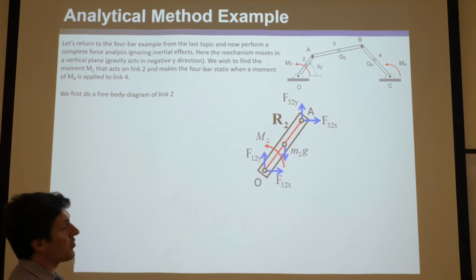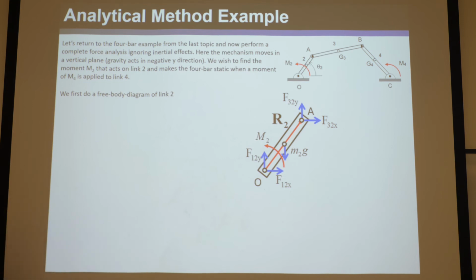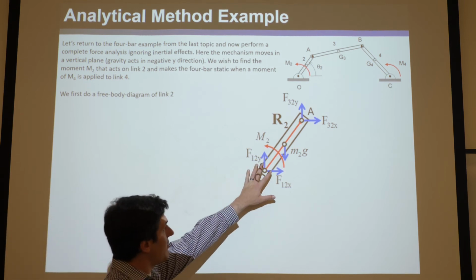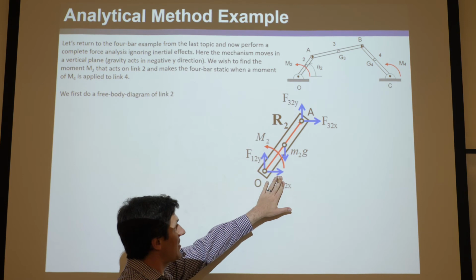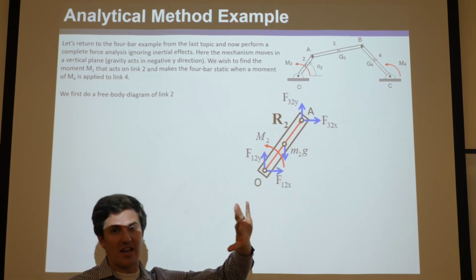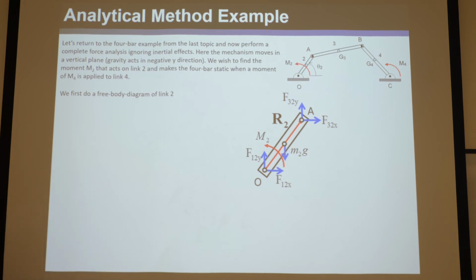Well, no, it's a pin joint, and by the way, you also assume they're smooth unless you're told there's friction in there, so there is no moment that can be imparted on that, just forces, and there could be a force in any direction, but we're going to break it into components. We're going to draw them always positive, and if we stick to that convention and it actually ended up being negative, it'll give us a negative sign.